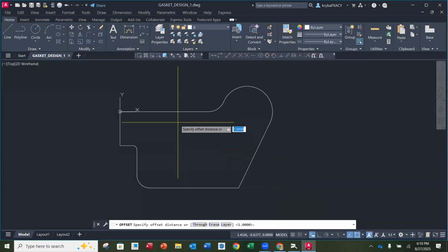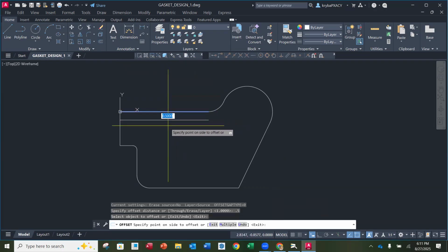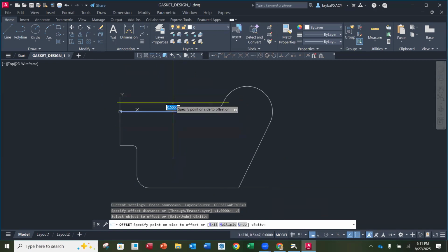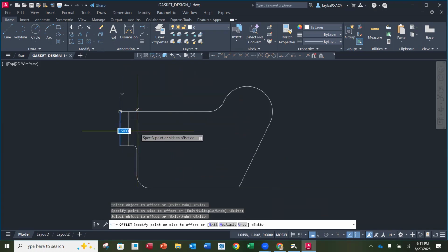Back over here. So I'm going to offset then each individual line. Don't do this. Just watch what I'm going to do. So I'm going to do 0.5, enter. And now I'm going to select the line and I'm going to push down, and I can go left, I can go above or below by just pushing my cursor, and I'm going to go down below.